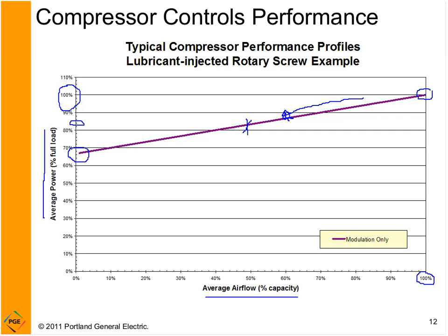Still required. The compressor's not doing a darn thing as far as helping my plant go. It's just sort of fighting itself. It's still maintaining full sump pressure, so it's still pumped up to that 100 psi, but nothing is coming out the check valve. I've essentially put my hand over the inlet, and it's just kind of fighting itself, not really doing anything. Okay, so that's modulation. What's next? Let's look at the perfect control.